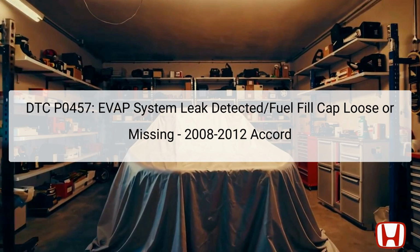The fuel fill cap is a crucial component of this system, located on the fuel filler neck of the vehicle. It serves to seal the fuel tank, ensuring no vapors leak into the atmosphere. When the system detects a fault, it triggers the check engine light and stores the code P0457. Before proceeding with troubleshooting, it's important to gather and review any freeze frame data or snapshots from the onboard diagnostics to better understand the conditions under which the fault occurred.